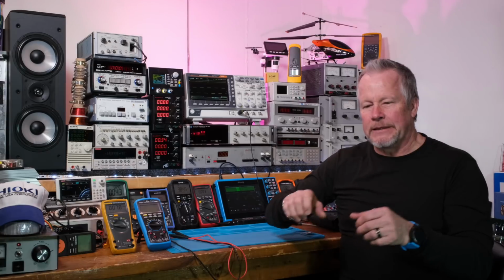But anyway, so yeah, your car's an isolated ground system, right? And it also shows how you can use a chassis, a multi-point ground system. You could just take something, tie it to the chassis. You wouldn't have to have that ground wire in your harness. You'd only have to run one wire out to, say, a radio to turn it on, right?